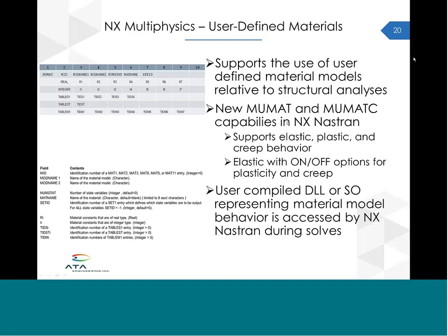Now, as you might expect, there are some setup steps you have to go through to enable this. In particular, you have to compile libraries if you're on Windows, or shared objects if you're in a Linux environment, to represent the material model in such a way that it can be accessed by NX Nastran during the solution.